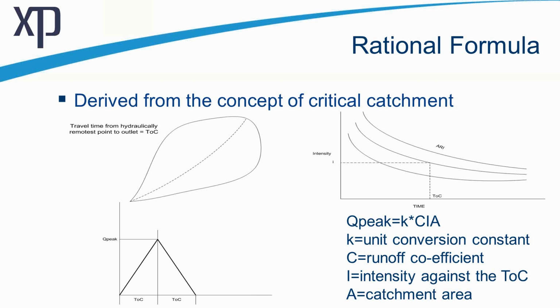You'll look at an intensity frequency duration table. If, for example, you had a 15 or a 25 minute time of concentration storm, you would expect a relatively high intensity compared to a long duration storm that may cover in excess of 24 or even as high as 72 hours from a design perspective.